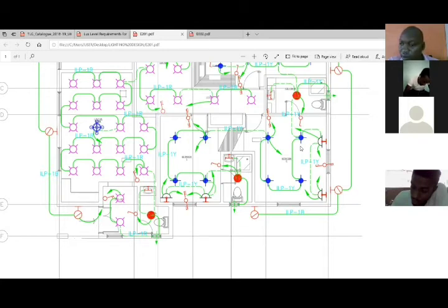12 over 21. So what does that give us? Let's quickly get that out. 0.57. Now, if I'm taking this value to my utilization factor, I showed you a sample of what the utilization factor table looks like the other time. If I take this to that table, I'll be getting around 0.6 as my value. So note it. I will take us back there and see how we select that from the table. Note that value, 0.6.